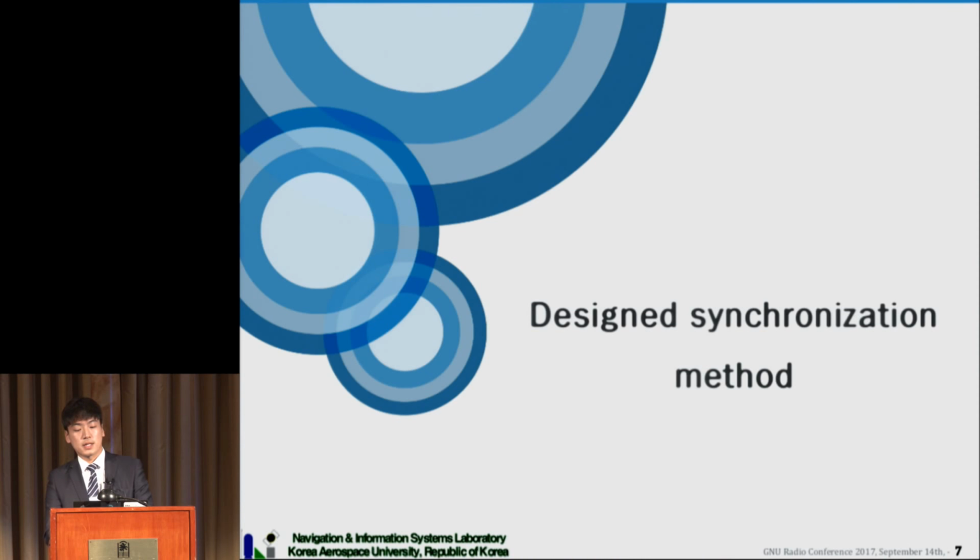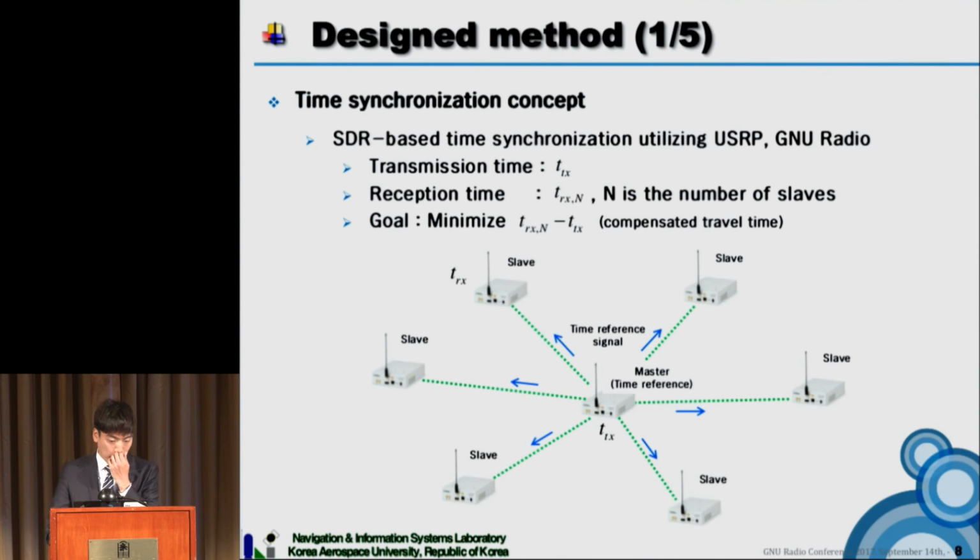Next, our designed time synchronization method. This is the basic concept of time synchronization. First, the time reference, called the master, generates the time reference signal and transmits it to the other slaves. Its signal transmission time is T_Tx.